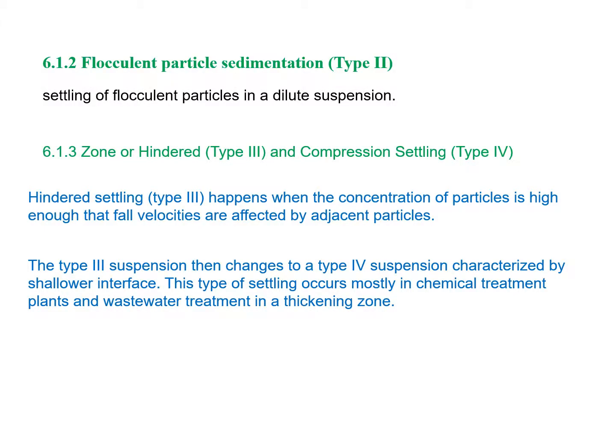Flocculation, particle sedimentation type 2. That was all of the calculations that we did before. It was just for one particle: settling of flocculent particles in dilute suspension, that is type 2. Zone or hindered settling will be type 3, and compression settling is type 4.